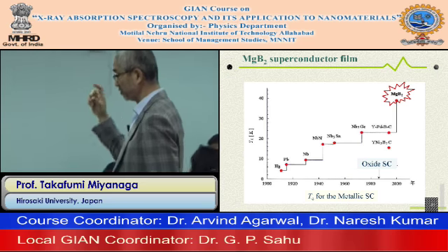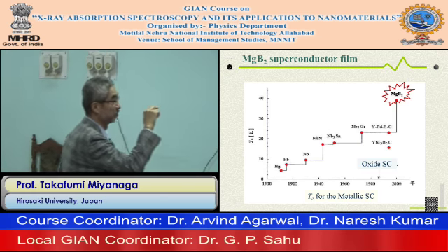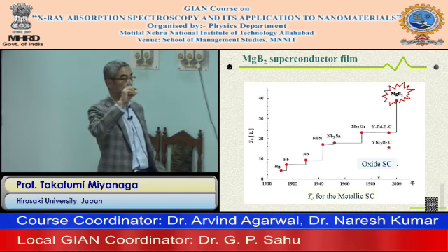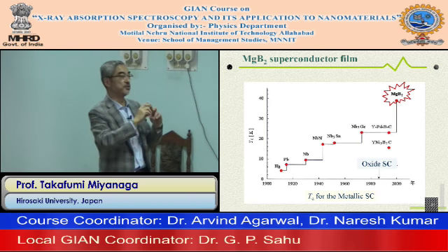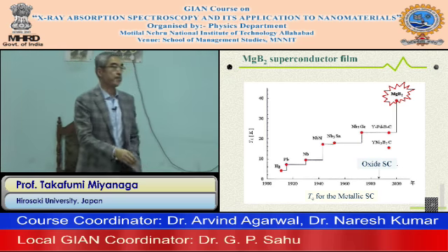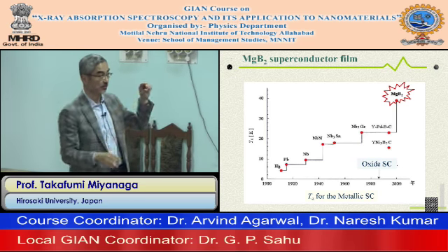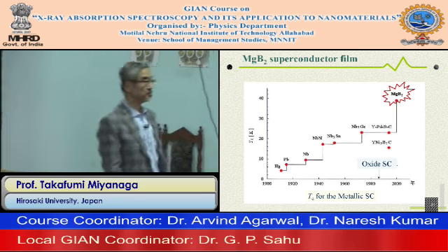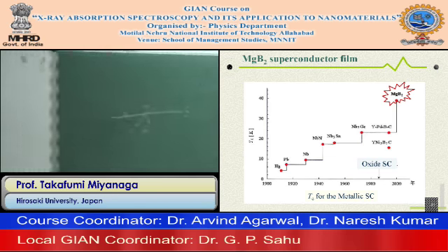The indium component controls the gap energy. In the case of a small portion of indium atoms, the gap becomes very large, so the emitting color shows a blue shift. Indium gallium nitride is essentially the active layer.